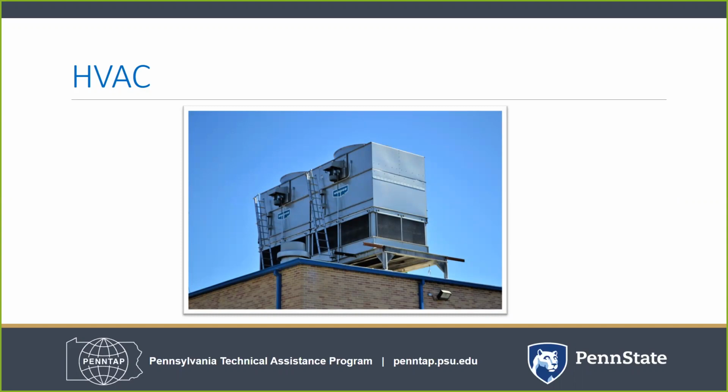For your HVAC system, find the root cause of your problems. Ensure vegetation is not blocking intakes. Implement a preventative maintenance schedule for filters, belt condition, walk-through inspection. Have a policy regarding open doors and windows. A seasonal setback on your temperatures, 65 and 72. In the cooling season, 80 and 74. Chiller temperatures, have as high as possible. Adjust economizer at different outside temperatures.